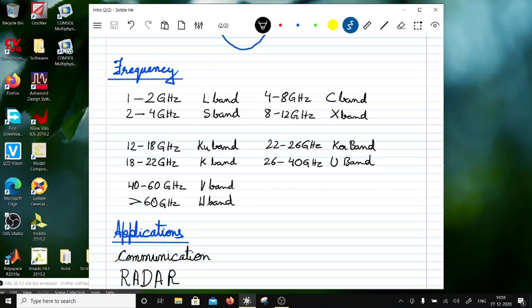For example, the ground is no longer a point, it's a distributed ground, right? So whenever you design something or cascade something, you always specify impedance with respect to a local ground instead of with respect to infinity, right? That's why in most designs, when you simulate, you do not use single ports. You are going to use ground reference ports. We will come to this when we design circuits and cascade them.